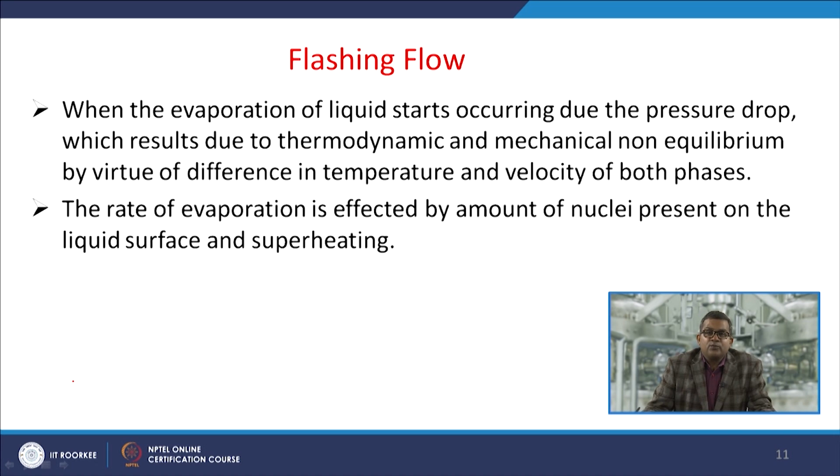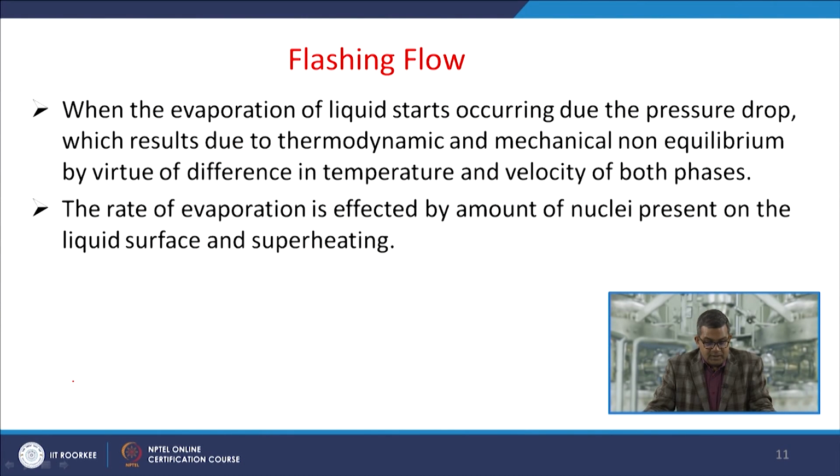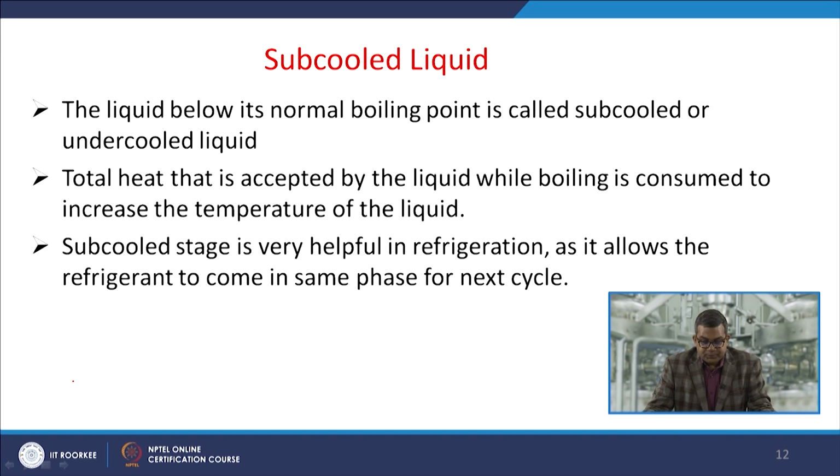There is a flashing flow when the evaporation of liquid starts occurring due to the pressure drop. Sometimes you may have a higher pressure and the fluid moves from a higher pressure zone all of a sudden to a low pressure zone. This results in thermodynamic and mechanical non-equilibrium by virtue of the difference in temperature and velocity of both phases.